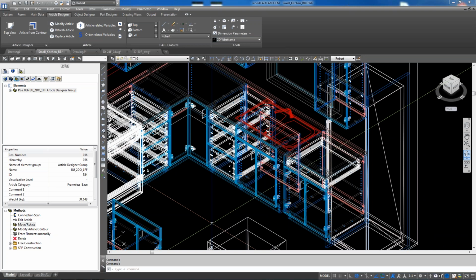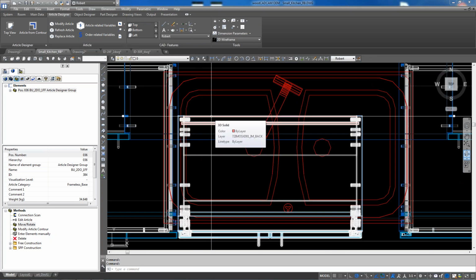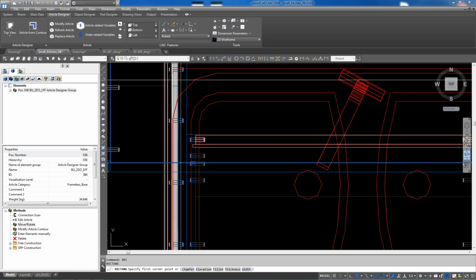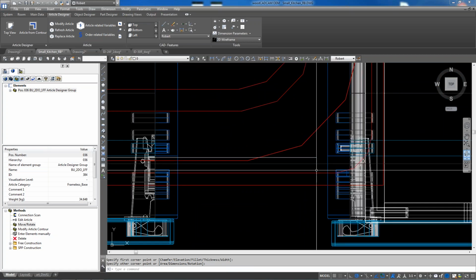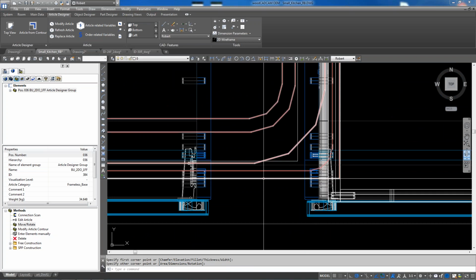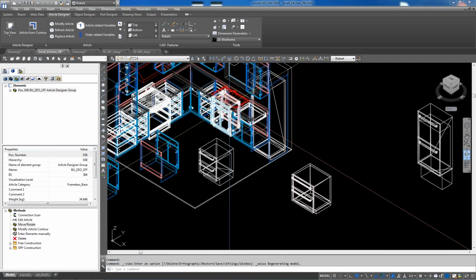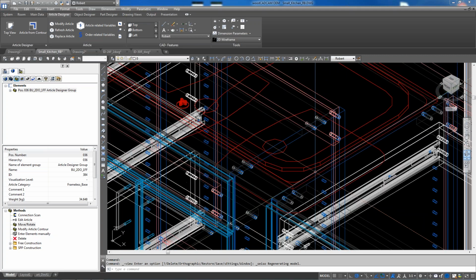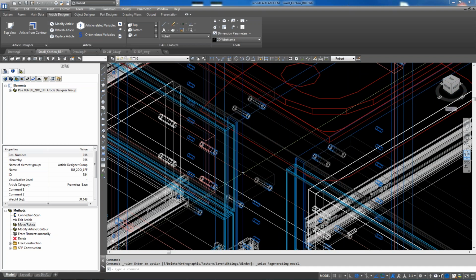So switch to your plan view, top view, world coordinate system. Just draw a polyline for the hole you want to cut. Could it be just a rectangle? Yeah, it doesn't matter. Whatever shape you want to cut. Obviously it's a sink, so it needs some rounded corners if you really want, but a rectangle will work. Okay, get an ISO view so you can see the deck of that top. And we're going to go to our details tab, part selection. Select that part.